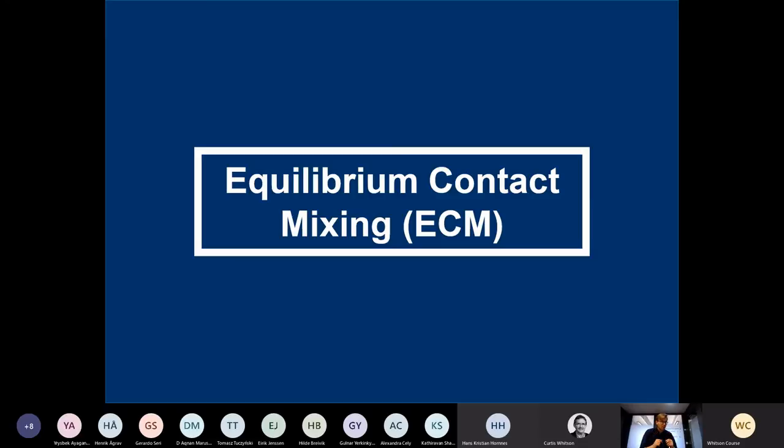Just remember that that's why we're going to talk about this, and without going into all the details of all the different cases, we'll try to focus on one particular case. I believe an oil, an initially undersaturated oil case, but the general ideas, and what I'm trying to convey with a few animations that were actually made by Marcus here on the side, are the key points of why it is important to do it like this and not just recombining the producing or the separator oil and gas at the initial producing GOR, and why that in some cases can be very different.